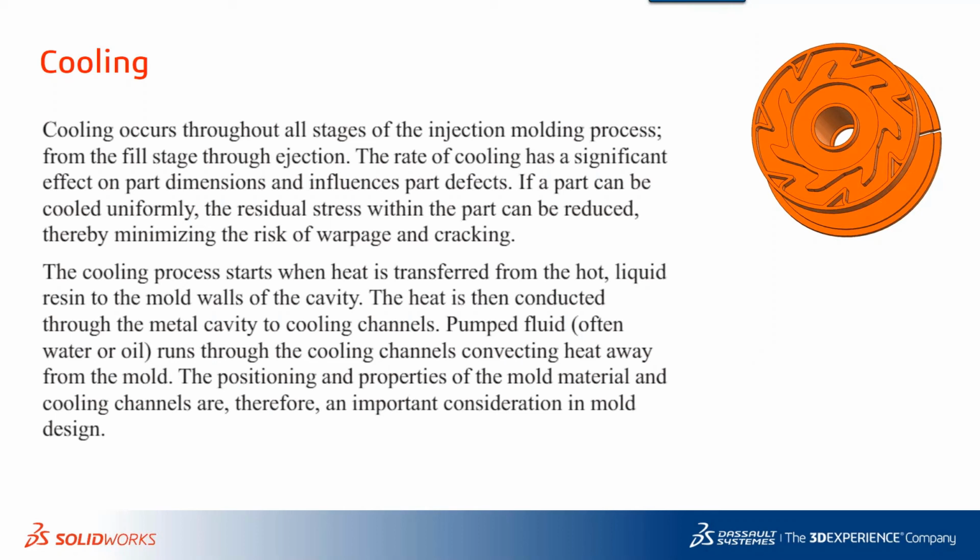So cooling lines happens throughout the injection molding process, right? Whether or not we intend to cool the part, it's going to cool because of two reasons: natural convection with the air and forced convection, which is your cooling lines. You're not going to have an injection molding setup without cooling lines.